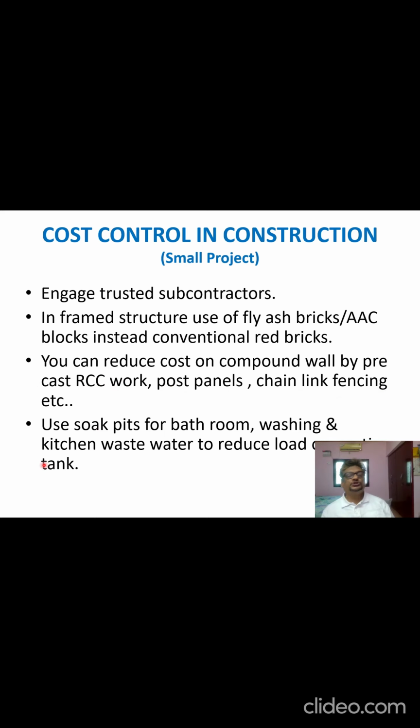You can use soak pits for the bathroom, washing and kitchen waste so that this need not be loaded into your septic tank. Thereby the construction cost of the septic tank can be reduced. So the use of soak pits is important.